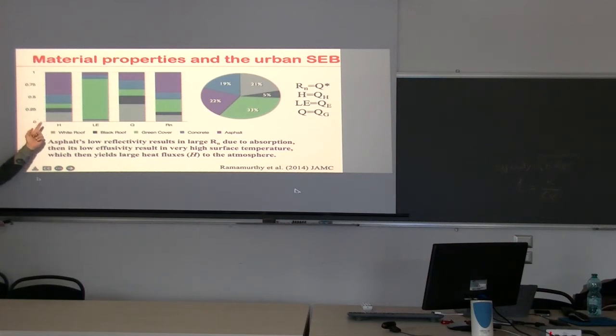And you'll notice that vegetated areas are 33%, but they hardly produce 10% or less of the sensible heat. Again, this 33% is going to give me about 75% of latent heat. All the evaporation is happening from the green cover. And the storage is mainly going to be from the concrete and the roofs, because in this case, these are old building roofs that are basically concrete. They're not very well insulated. So they store a lot, and that shows up here.